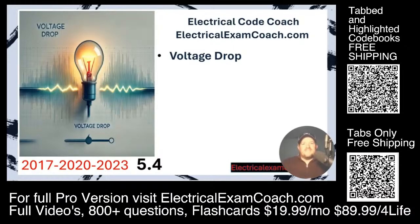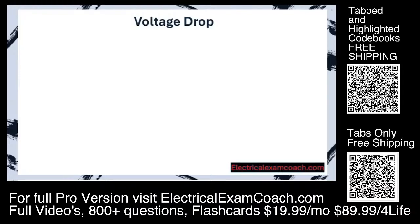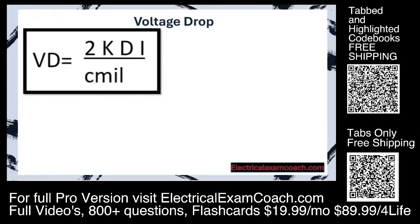Let's get to it. If you were to do an internet search for a voltage drop formula, you would likely find this one right here. Voltage drop equals 2kDI over C mil. And that is an excellent formula, and it's actually the one that I use. But I've rearranged it so it's easier to remember.